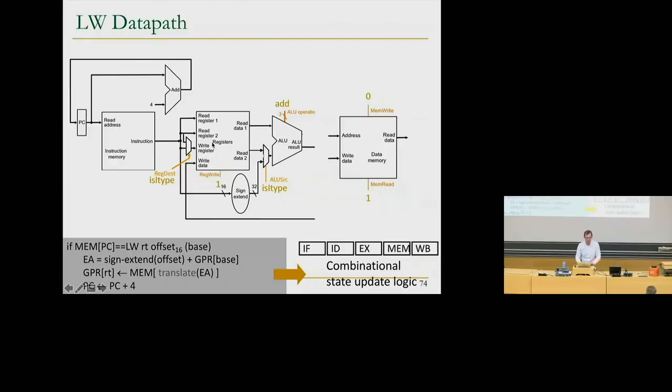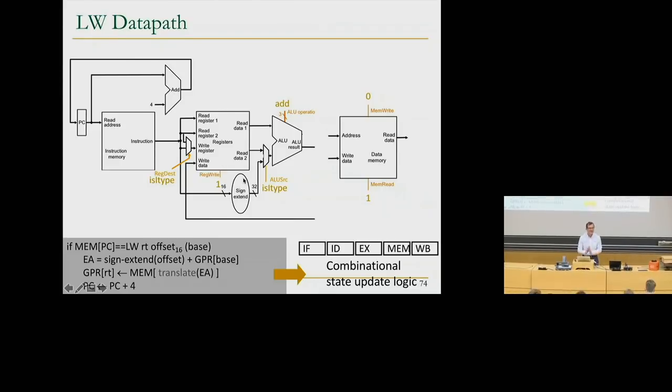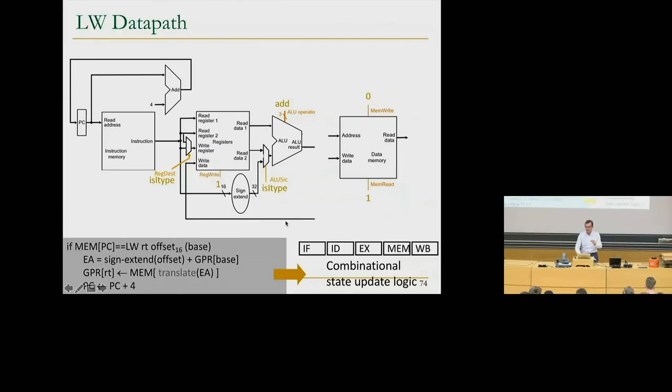And we already did that, we added this MUX for I-type instruction. Load word is essentially an I-type instruction. So you set the control signal similarly over here. And we need to ensure the register is written, so of course, we set the register write signal to 1. That's true for all instructions where you write into a register. Makes sense, right? So that's our load word. Basically, all we needed to do on top of add immediate is access memory using the ALU result and write the data coming out of memory over here.